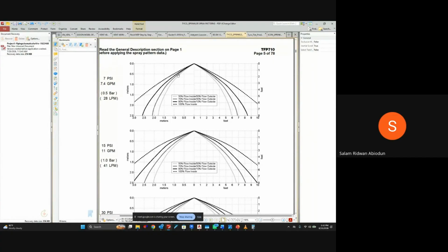And that was what actually brought the question. You cannot vary the hazard in an office space. You cannot have office space hazard one, unless they are doing different things there. Maybe in this office space they are just reading and using laptops. And in another space, maybe they have documents that they don't even want to risk burning at all. Then you can increase that hazard to maybe ordinary hazard 2. Maybe in the kitchen, you can increase that to ordinary hazard 3.